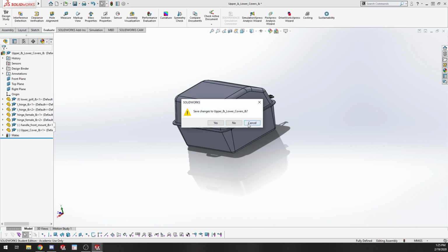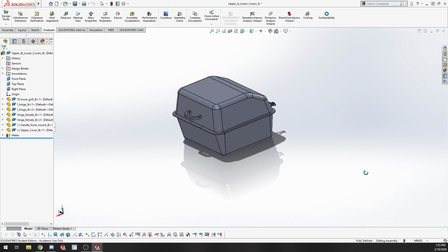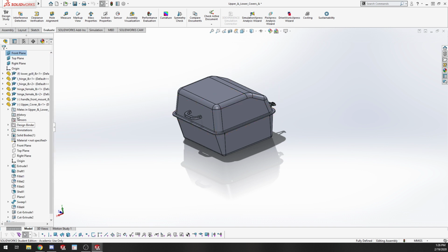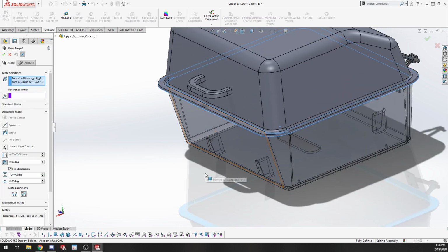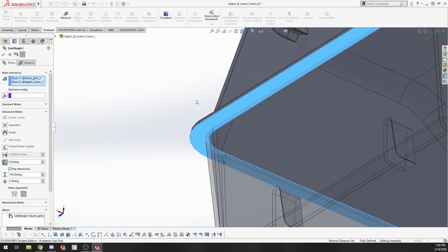What's up? Like that last one, you said 0. So that when it's fully closed, it's 0. Yep. How does SolidWorks determine that? Is it off of whatever plane you tell it? Yeah. So when I went in, let's see, where was that mate that I added? Limit angle, edit feature. What I did when I selected those two was I selected 2 faces, and it's just the angle between those faces as it goes up and down.